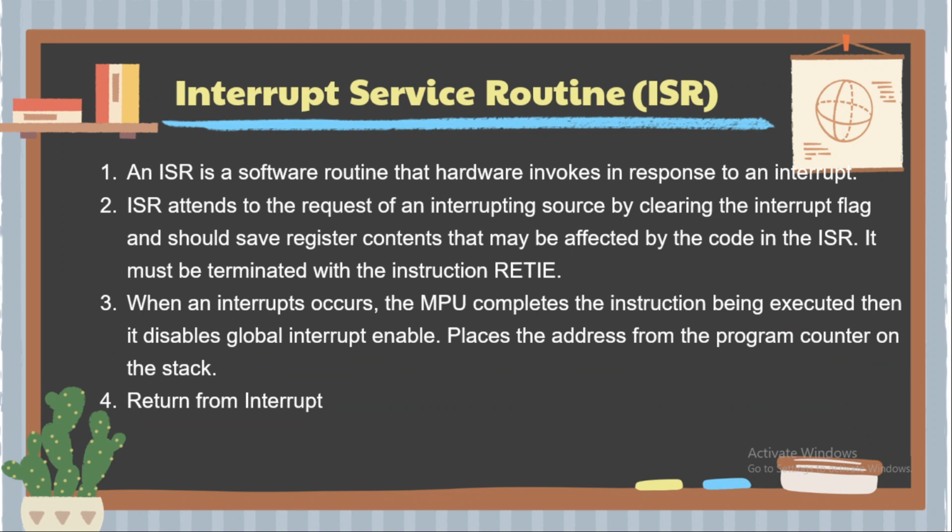Then what is ISR? ISR is the interrupt service routine, and ISR is a software routine that hardware invokes in response to an interrupt. ISR attends to the request of the interrupting source by clearing the interrupt flag and should save register contents that may be affected